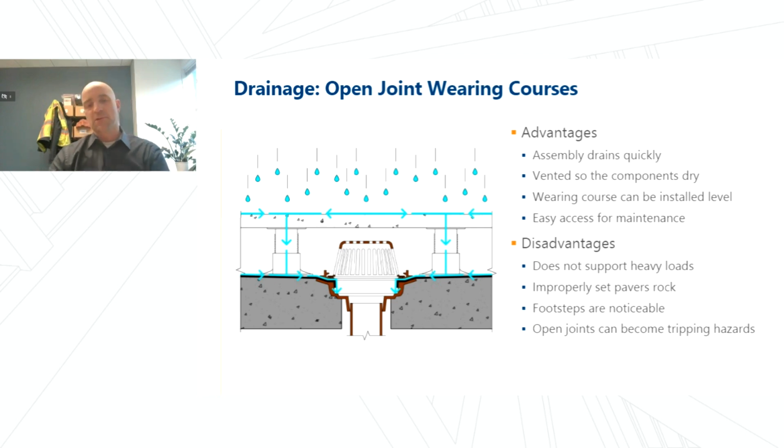The surface of the structural slab should be sloped at 2%, which is approximately 1/4 of an inch per foot. It's both code required and good practice. The reason being, with construction tolerance and deflection of the slab, if we specify 2% and we get 1% slope, the water will still move toward the drain.